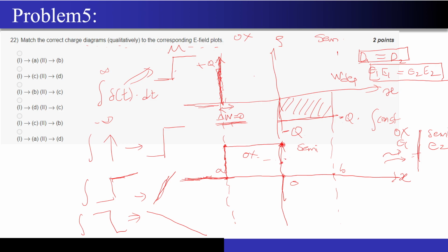There can be a drop or there can be an increase, right? Now how will I decide whether there will be a drop or an increase in the electric field? This equation will actually help me. So now I will apply this equation for this oxide-semiconductor interface: epsilon oxide times the field in the oxide is equal to epsilon of silicon times the field in the silicon.